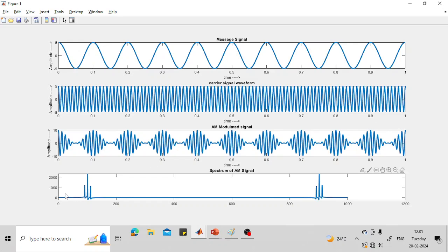Okay, and you can observe here, if modulation index M is equal to 1, then these sidebands will have half the amplitude of the major lobe. That major lobe, the carrier frequency lobe, is this much, right? So the sideband will be half, because what is the formula for sideband amplitude? The sideband amplitude formula is EC into M divided by 2.